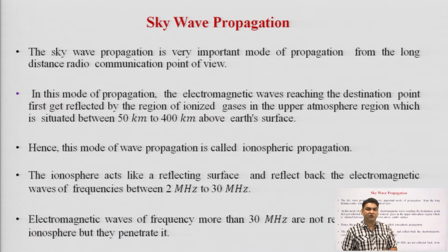The refractive index of the atmosphere in the tropospheric region is considered as 1 because it is known as the standard atmosphere, although just above the earth's surface it is not exactly 1, it is somewhat higher than unity. The refractive index gradient, dn by dh, is the gradient of the refractive index with respect to height.